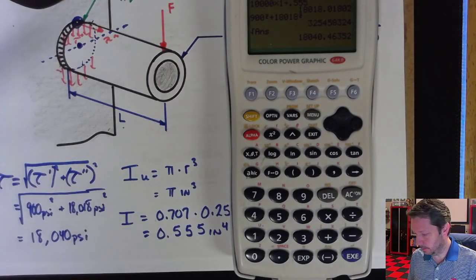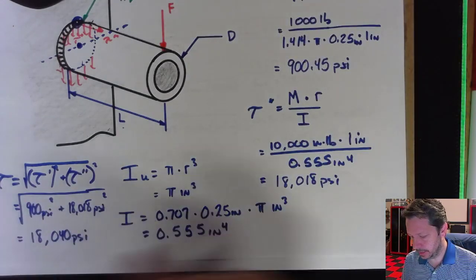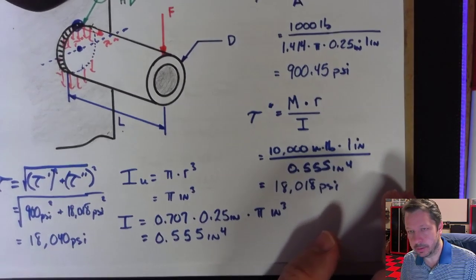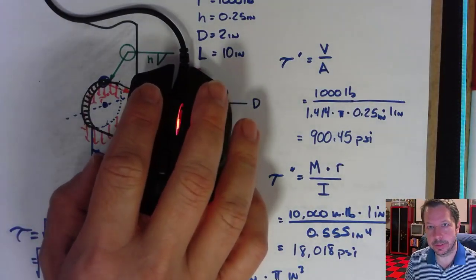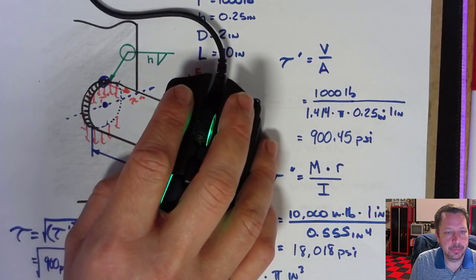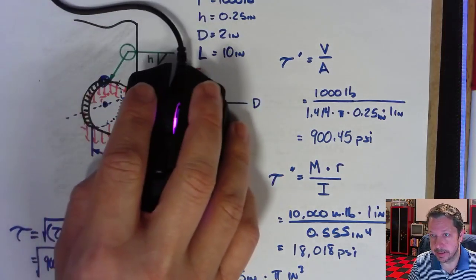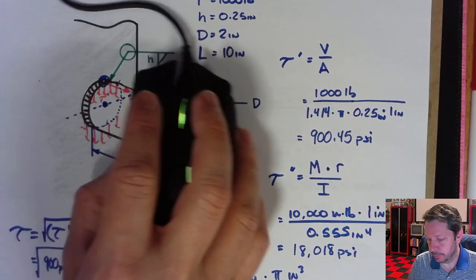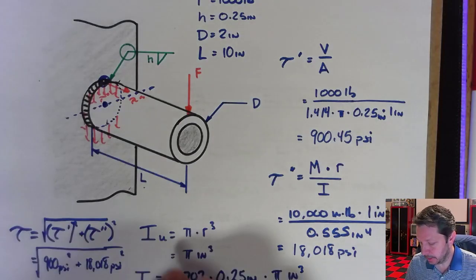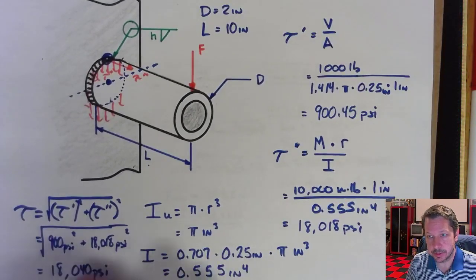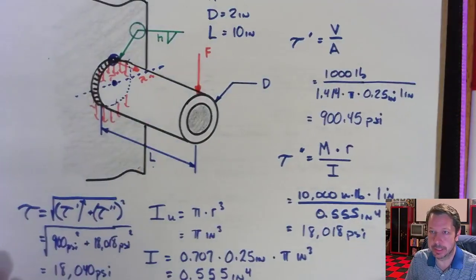Now those numbers are getting really close to, if we were using that E60, the allowable shear stress, which might be around 16,000 psi. I don't remember offhand. We're not actually doing any designing, we're just doing analysis right now, but you could check that out. And that doesn't include any mixing that might have come from whatever parent material we had back here. So we were getting close to probably some dangerous situations with these welds that we analyzed today. We didn't design them. They were already set in their dimensions.